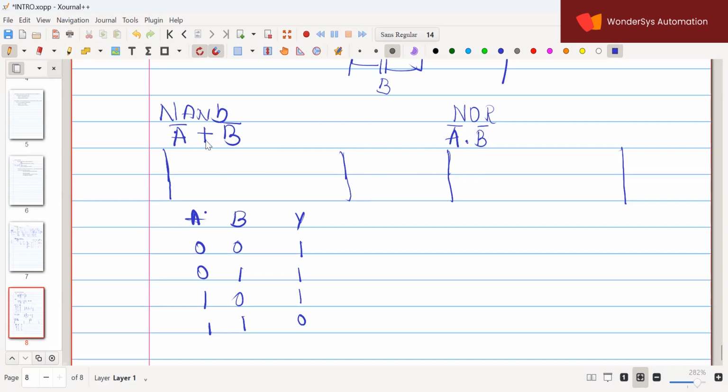Now, since it has a plus, but it is not A, it is the complement of A because it has A bar, therefore I have to use an NC switch. Since it is a plus mark, I have to use a parallel combination. Since it is a complement, a NOT operation, I'll be using two NC switches in parallel connection. Okay, where did you get confused?